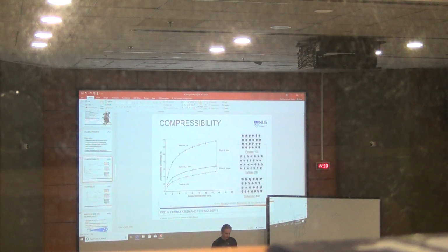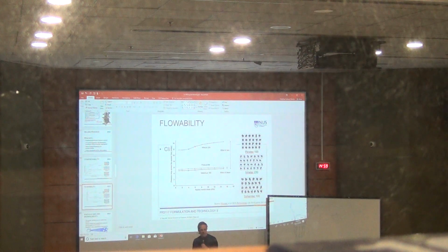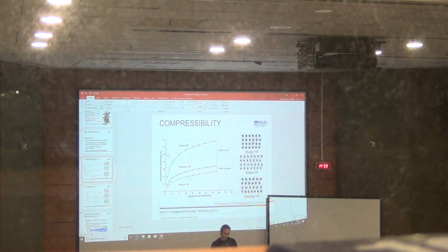And here we, for example, also looked at compressibility percentage and flowability percentage, because the particle size has a certain impact, and milling processes also generate that. When I talk here about compressibility percentage, it means the compressibility index. Now you know that, for example, the effect of size is very huge, very often, on the compressibility of the powder. Usually when you have a larger powder, you may see a higher degree of compressibility here. But in this case, it is not a good thing, because it refers to the USP characterization of compressibility index.